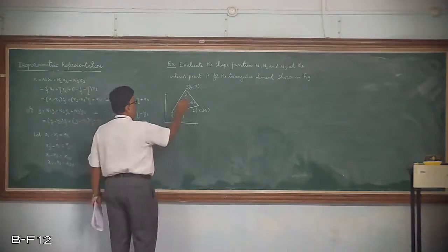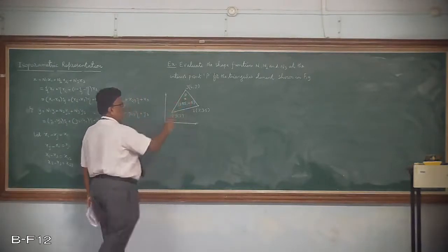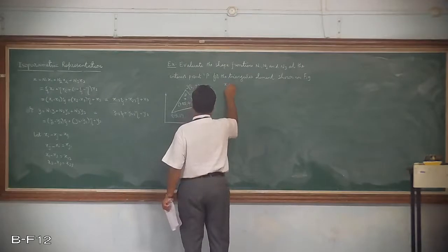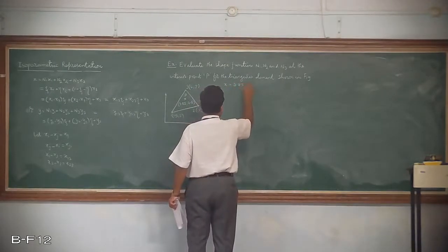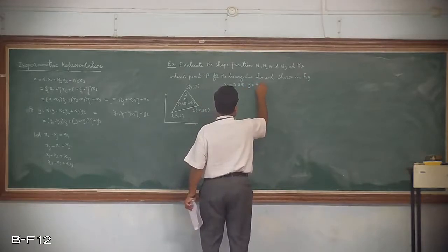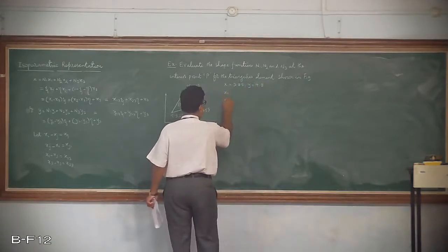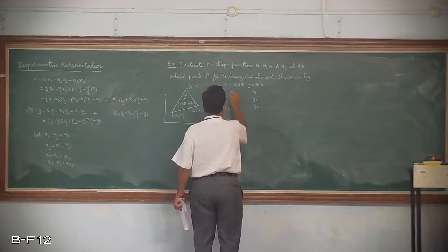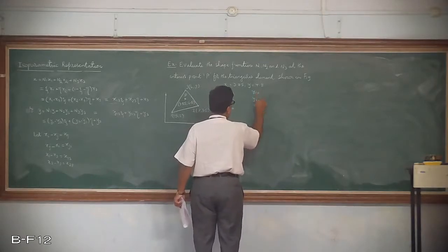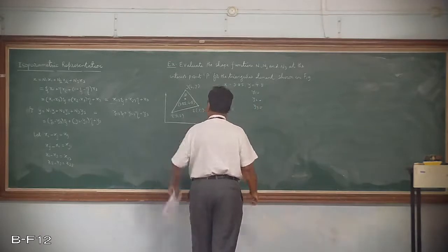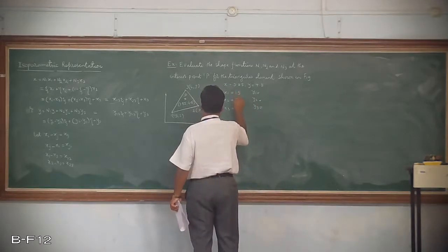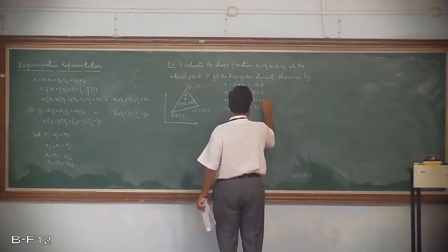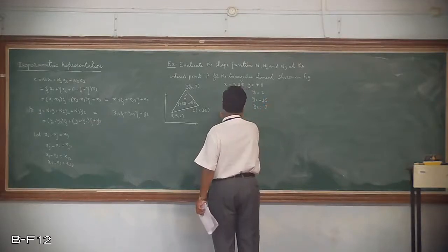We need to find out the three shape functions at this particular point. So let us quickly note down the known quantities. x we know is 3.85, y we know is 4.8. Let us go to x1, x2 and x3, and y1, y2 and y3. x1 is 1.5, then 7, and then 4. And y1 is 2, 3.5 and 7.